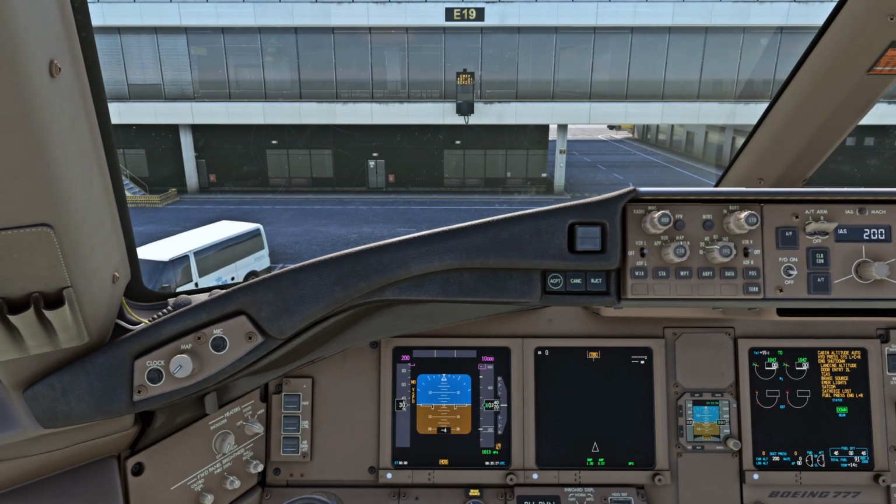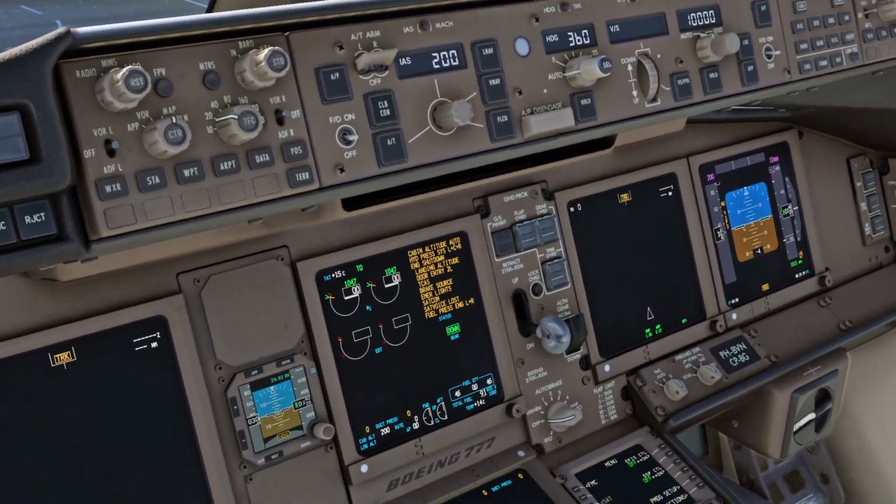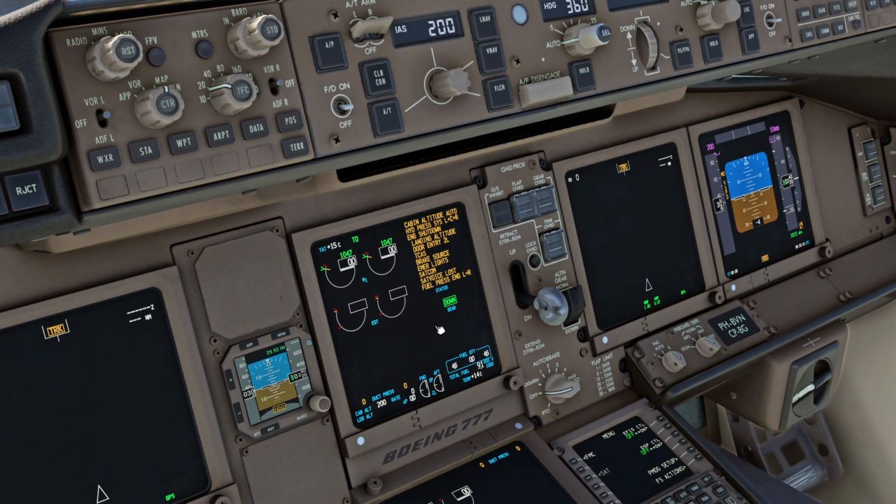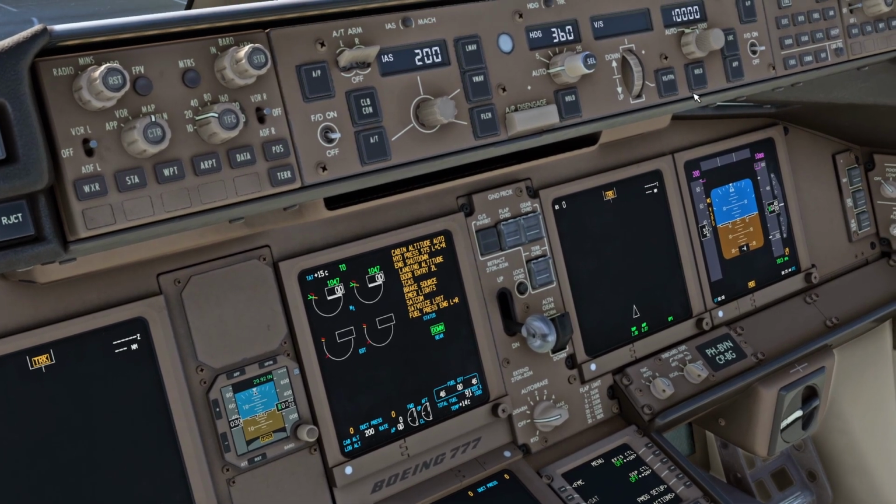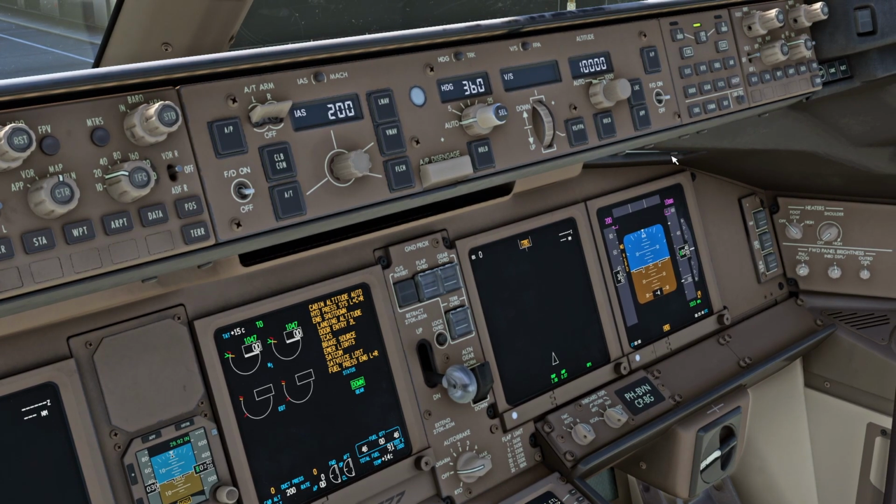There are a few other items that we're gonna have to check here. Now the ICAS display on your 777 is your friend. It shows all kinds of advisory, caution, warning messages about the airplane. Now it's normal to see some of the messages right here because the airplane is not started up, but it's good to scroll through them, especially if there are multiple pages. You can do that using the cancel recall switch, or you can just remove them or recall them by pushing this switch over here. So you can check all what's over there.